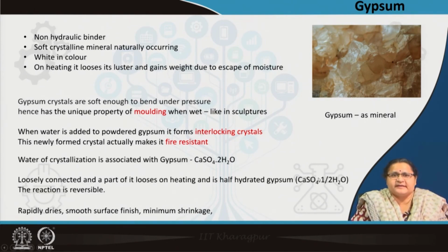Now, this water of crystallization, what we were talking of, loosely connects with gypsum, but when it is heated, it becomes half hydrated gypsum and loses 1.5 molecules of water, and these reactions are very reversible. It rapidly dries, gives a smooth finished surface and minimum shrinkage. That is very important, minimum shrinkage. So, it does not lead to cracks. Shrinkage is the cause of cracks.